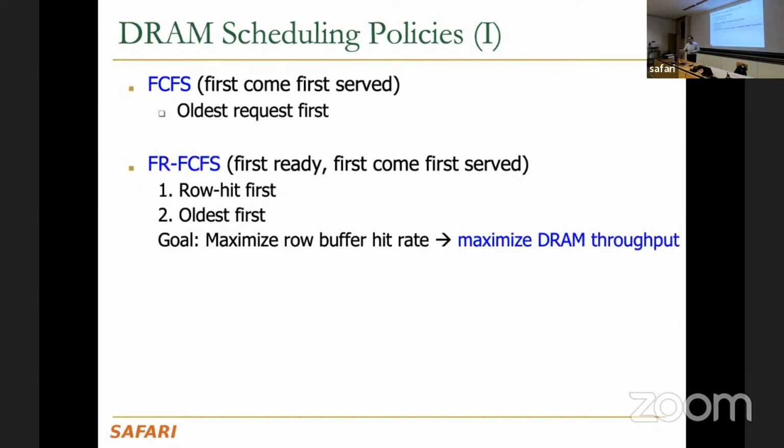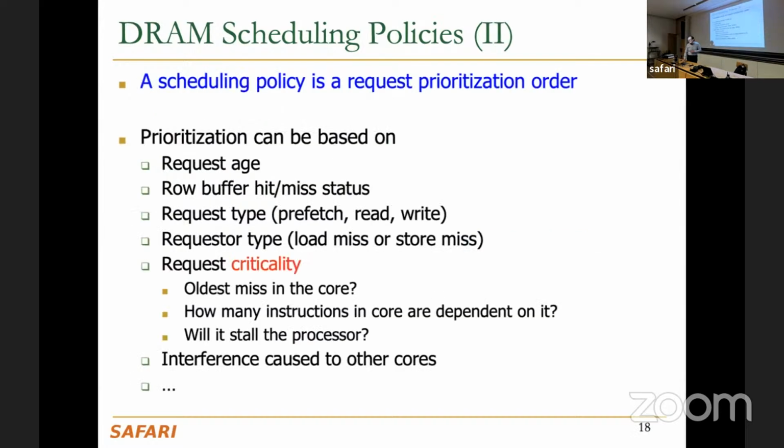So on top of this, of course, existing memory controllers need to think about write, read, right? Because you cannot do reads concurrently with writes because of this write to read and read to write delays and the fact that the bus operates only in one way. As a result, there's also another policy over here to decide when to schedule writes and when to schedule reads. So think about that in the back of your mind. So things get complicated. But then you can do more sophisticated policies.